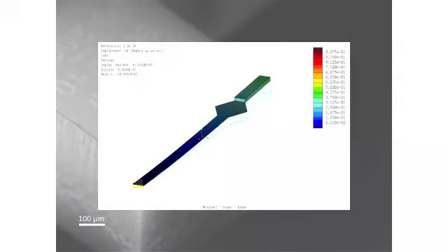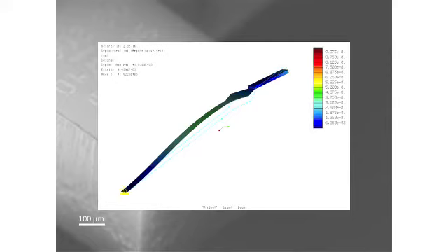This is just to give you an idea: we use the first fundamental mechanical mode to do our measurements, and this is the profile of the first mode. This is how it oscillates, not very exciting. Of course, the cantilever has higher modes, and this is just the second mode, just to give you an idea of what it looks like. We designed the cantilever with this very large mass on the end in order to suppress this and even higher order modes. I can tell you a little bit why we do that, but essentially we can treat the object as only oscillating in this first mode that I showed.